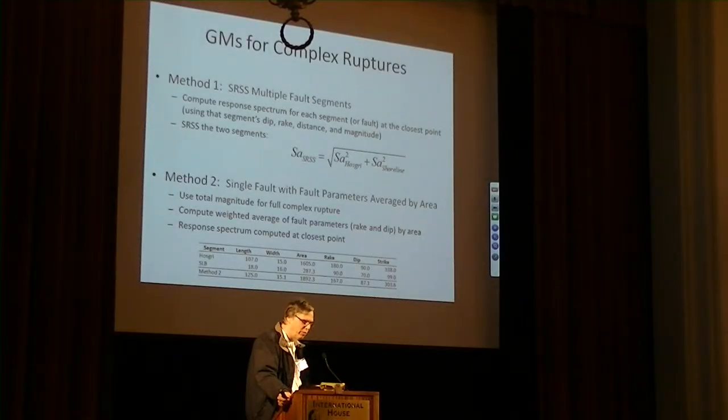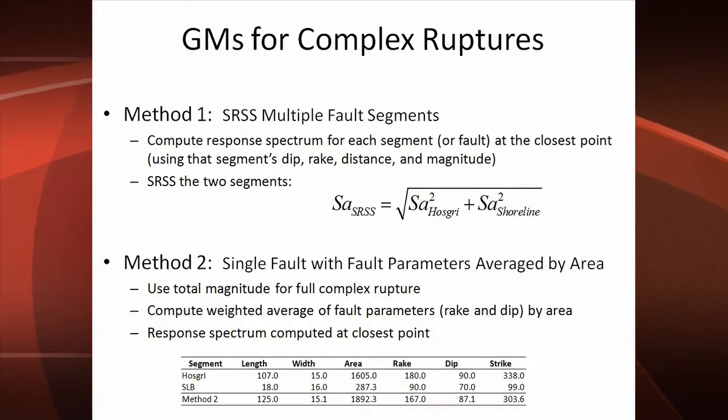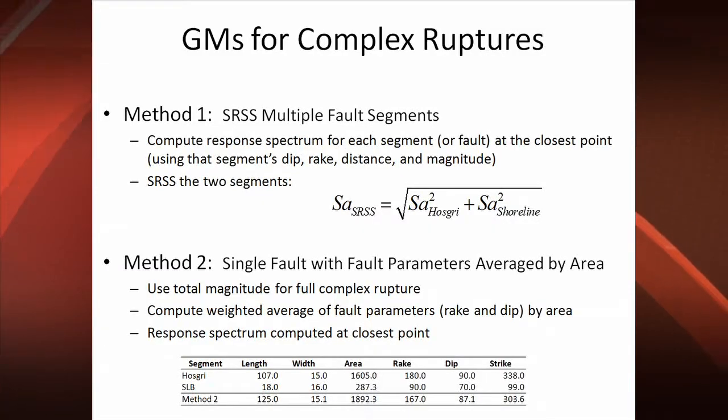Quick question. Does the SRSS work for long periods? Long periods? Yeah. Katie, what period range did you guys check? Did you check long periods as well? Yes. I think the answer is yes. Oh, I'm surprised, because it shouldn't. How long of a period? Well, 10 seconds. But maybe in the case the magnitudes are so different, maybe one dominates, so it doesn't matter. But it's a little surprising. Anyway, good. At 1 or 2 seconds, it still works.